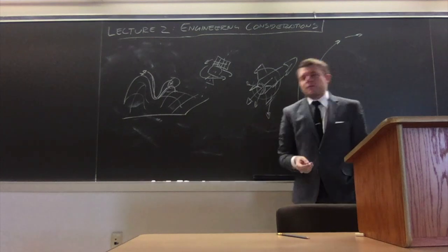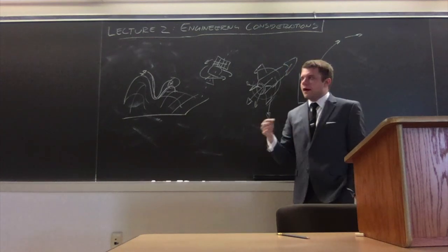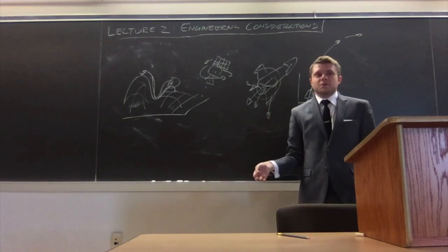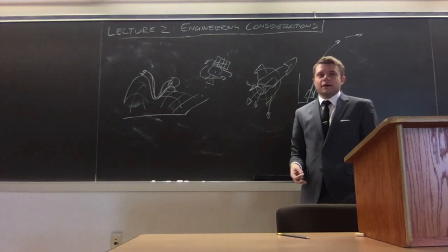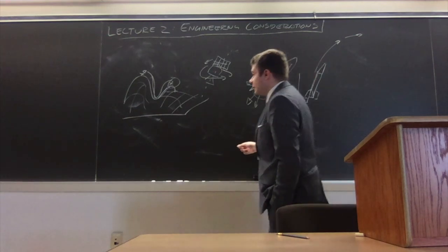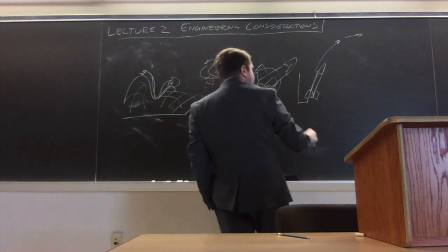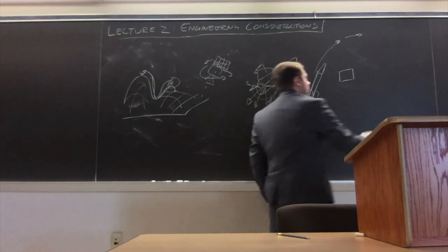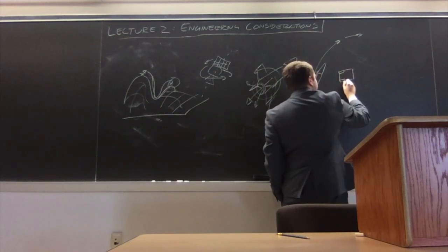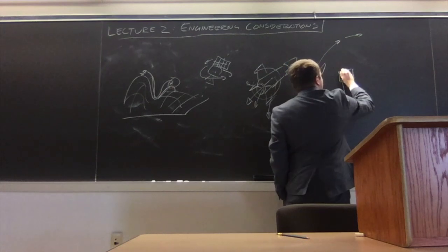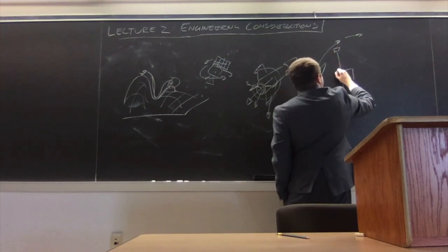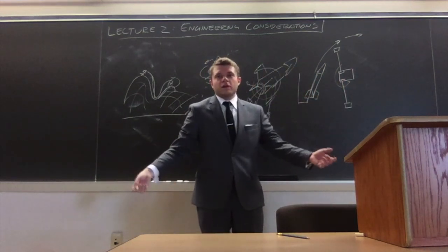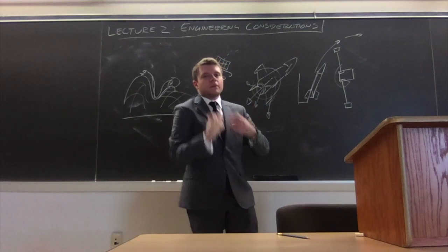Problem is that at some point you want to stop spinning. If you're taking pictures of something and you're going like 760 rotations per minute, it's a little fast. I don't even know if even with the fastest shutter speed, the capturing is meaningful. So what you do is when you're in space, and you've probably heard of this before, you use conservation of angular momentum, you get little weights on cables, and you release the weights on the cables. And you immediately stop spinning, or at least slow down greatly. And this is from conservation of angular momentum. You think of the figure skater drawing her arms in to speed up and putting her arms out to slow down.